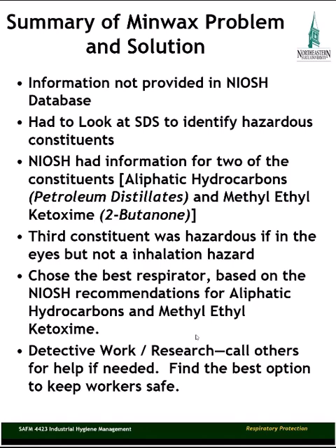It will end up in your finish, and you can't have that. You can't have any air movement that you would get from a conventional ventilation system. If you have that air movement, it ruins the quality of your work. So that leaves you with personal protective equipment. That leaves you needing a loose-fitting hood with an air-supplied respirator in the continuous flow mode.